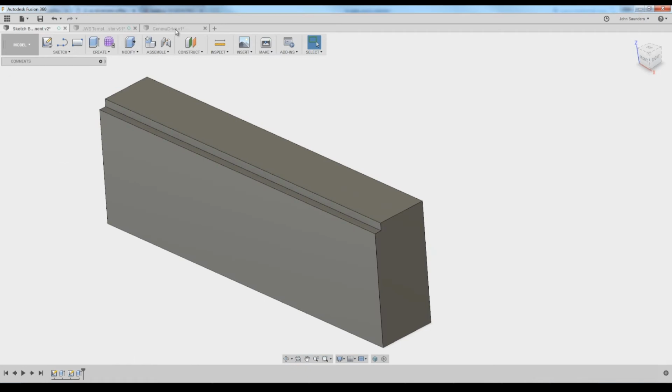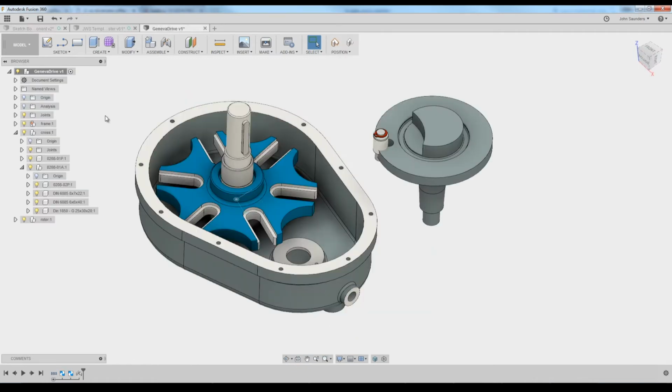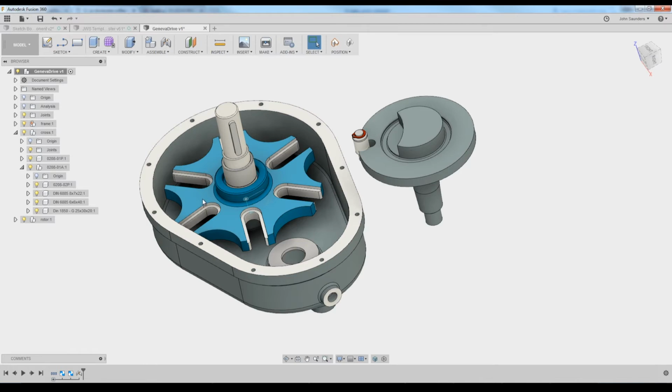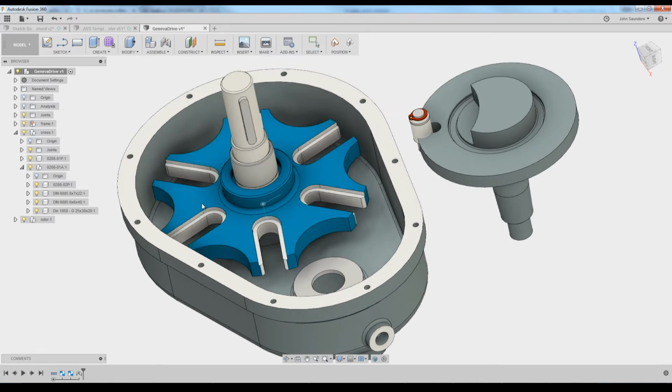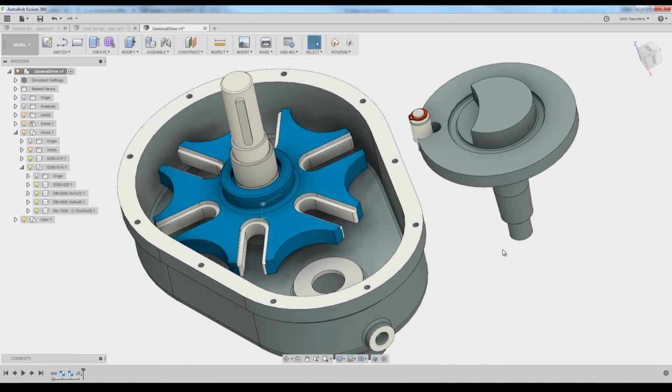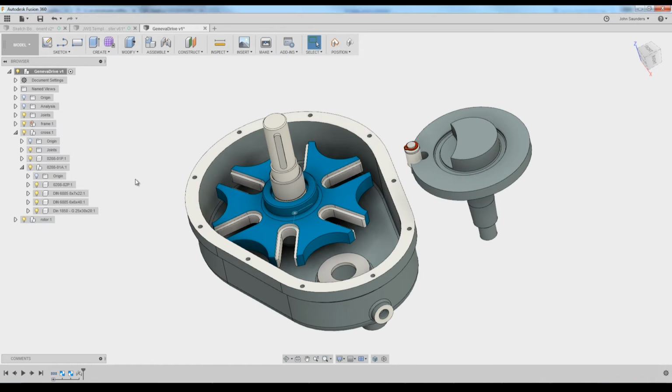It's important because as your parts get more complex, like this Geneva drive, you really want to make sure that your sketches were done in the correct component. In other words, I don't want to create a sketch to modify this gear, but have that sketch accidentally live in the component for this part over here. If you're not sure which is which, click on it. When you click on it, take a look at which item in the left has this new row of dots below it. See, underneath rotor, we get those dots. Same thing, I'll click on the blue gear, and you can see it expanded across, and then this component right here.